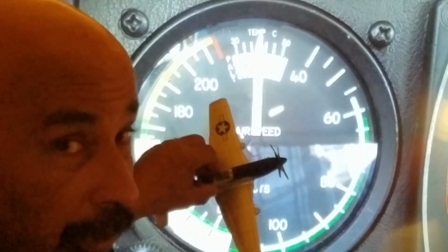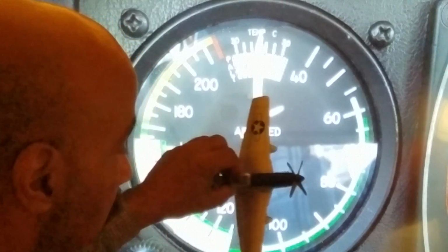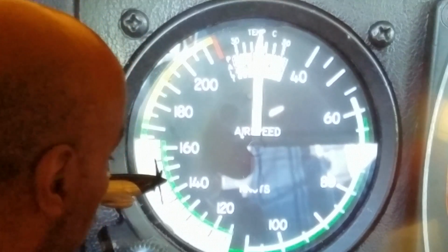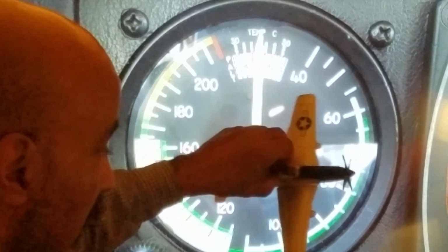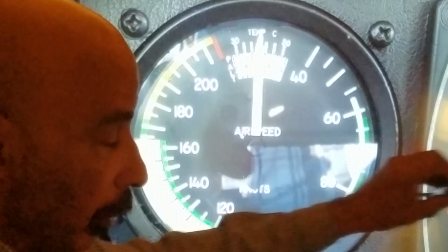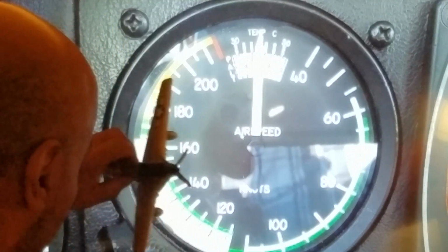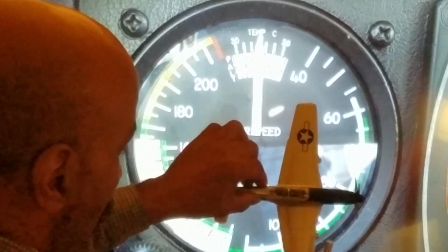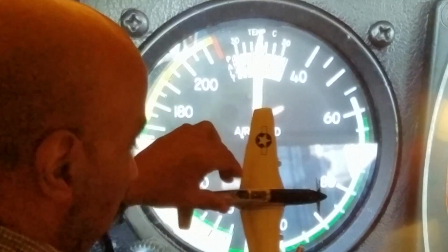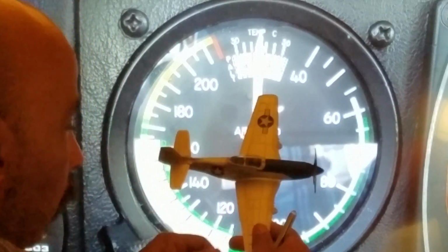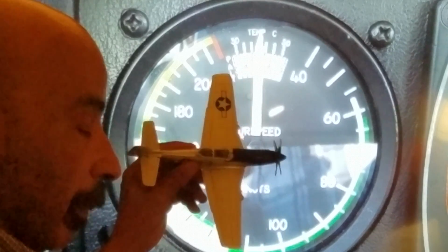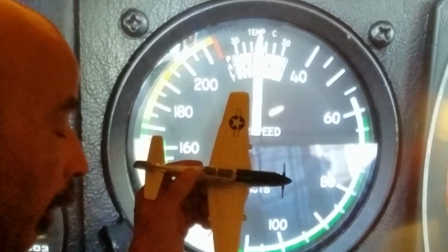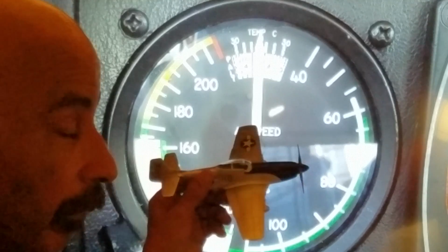Stalling does not have to do with the engine. We're talking about the wings stopping flying. They don't fly anymore. An accelerated stall means you are going fast before you make the bank and yank on the control and you cause the aircraft to fall in the direction you were already traveling. To recover from any stall, you would push the nose down or allow that wind to begin to flow again on top of the wing. Anyway, maneuvering speed is typically the airspeed at which you can do that full yank, full travel of the flight controls without doing any damage to the airframe of the aircraft.